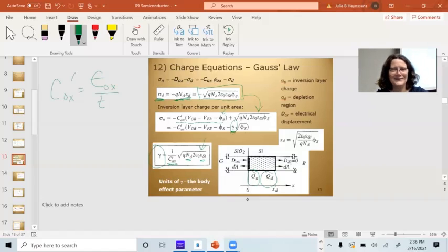Yeah, it's more than just hafnium oxide. It's nitrated hafnium oxide. I just did this in 280. I can remember that. Okay. So that's the epsilon of silicon, where silicon is the subscript, right? For COX, it's the epsilon of the oxide. For Si, it's the epsilon of the semiconductor material. So they're different relative strengths there.